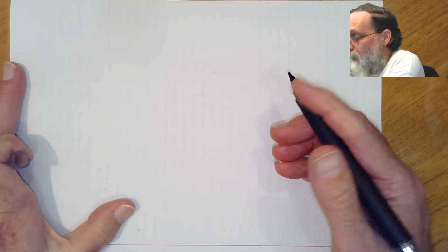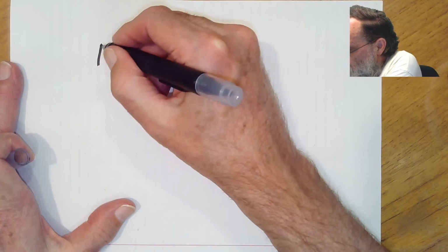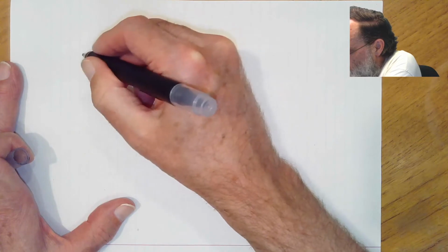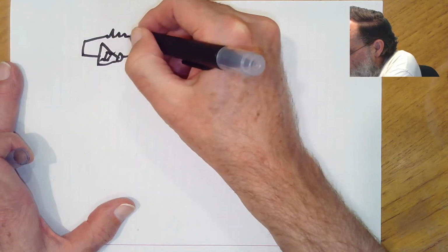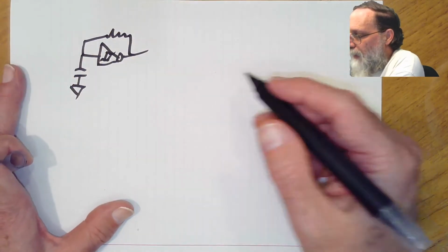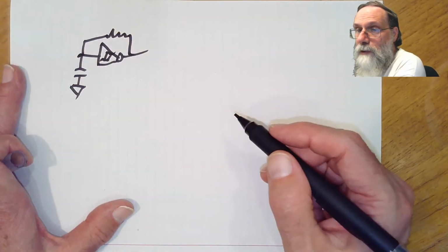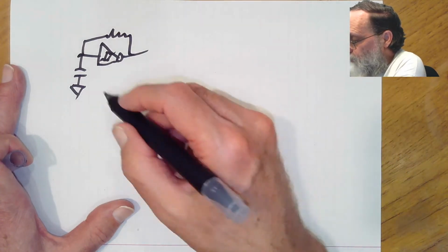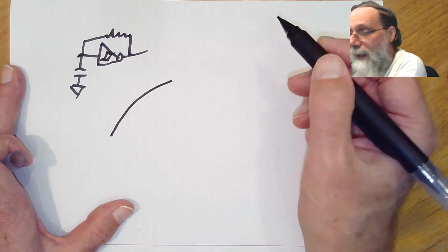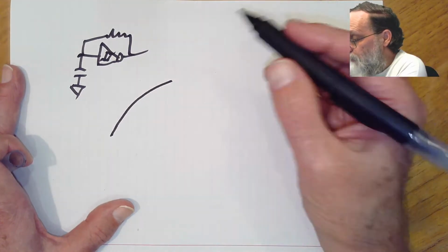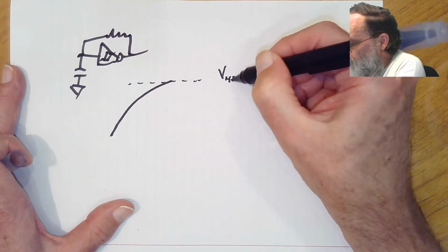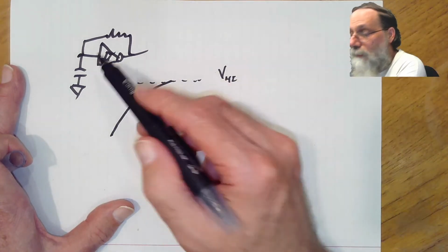We saw a hysteresis oscillator, which consisted of an inverting Schmitt trigger, a feedback resistor, and a capacitor. And if we looked at the voltage on the capacitor, what we got was that when the output was high, we would get the capacitor charging, RC charging constants, until we reached the high threshold of the Schmitt trigger.